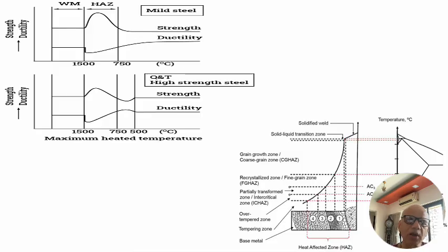But at the same time, since it is a metallic material, it has a coefficient of expansion, conductivity and other associated properties of a particular material. If we are not able to take care of those properties and manage our heat, our cooling, and our fixturing, we cannot ensure that we not only protect the parent metal, but also protect the weld and get a good weld here. The heat affected zone is very thin, maybe from a few microns to 2, 3, 4, 5 millimeters depending upon the thickness and the type of material.